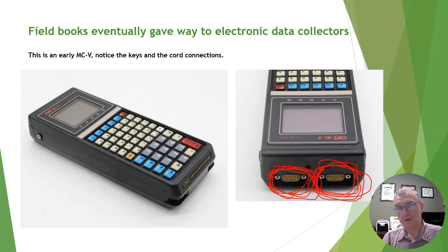For example, I think of a 40-acre field topo that I prepared in the late 1980s, maybe around 1990. Took about 7 days in the field. Took about 2 days in the office just to manually enter all the field data into a raw data file so that it could be reduced before we ever reduced the data and had a closure to check or could start plotting points. So that was the advantage a lot looked at.